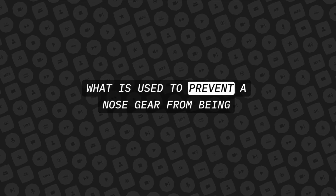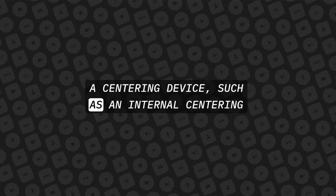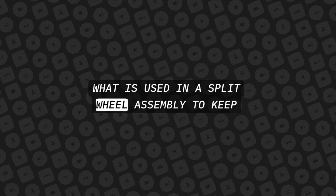What is used to prevent a nose gear from being retracted with the wheel out of the center position? A centering device, such as an internal centering cam or external tracks that straighten the nose wheel before it enters the wheel well. What is used in a split wheel assembly to keep air from leaking between the wheel halves?